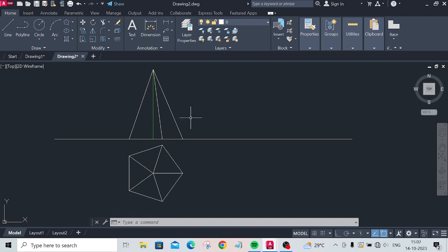Now the plane is cutting the pyramid perpendicular to VP. Then the cut-off will be made in the front view. Parallel to HP and perpendicular to VP means that plane will be a straight line in the front view. And it passes through the axis at a distance of 25 mm from the vertex, that is the top. From here, top 25 mm.